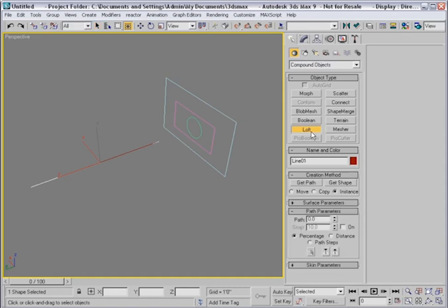By doing that, we've defined the path. We actually could select a shape at first, but I recommend against it. It's better to select the path at first, because the 3D loft object will exist right on the path.